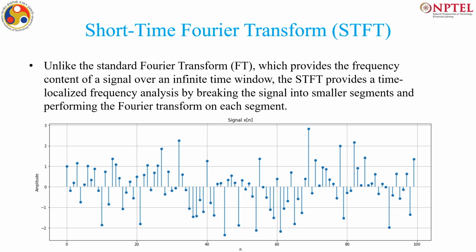Here, say we have this signal, and if I do the DFT of the whole signal, say this is of length 100, I will get the frequency content of the total signal, but I do not want that. There are some events like this and this where there are a lot of variations, and I need to capture that. So, let us select a window which is of size 20. Typically I will have 5 windows which are non-overlapping. Of course, we can also use overlapping windows.